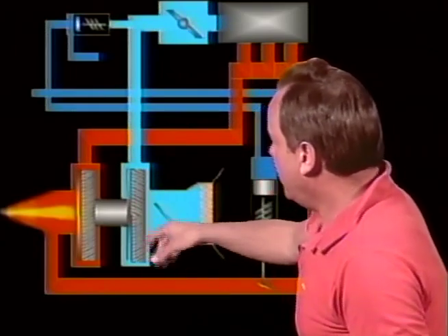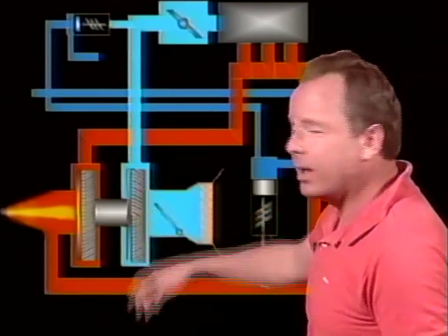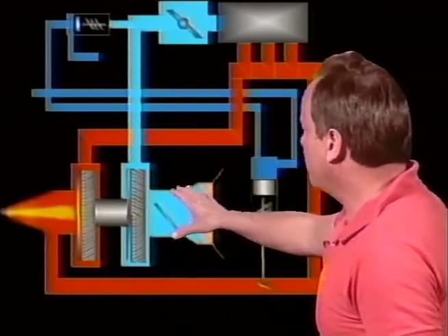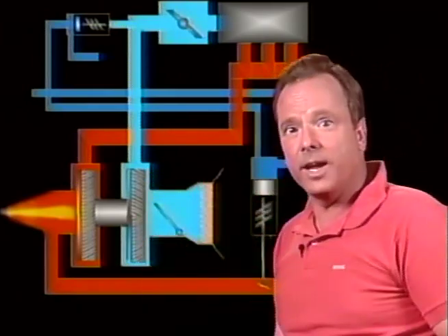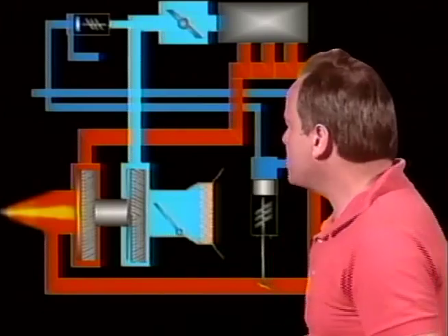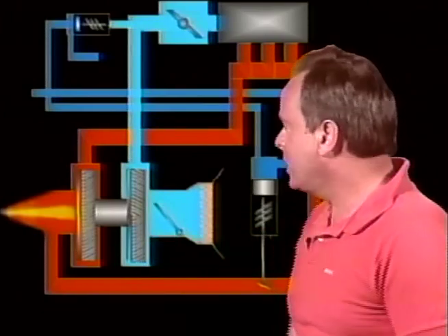impeller. And if you don't want to supercharge a lot, you'll select low-speed impeller, and if you want to supercharge an awful lot, put a lot of increased manifold pressure there, you'd use then high impeller in that particular case. They're going to ask you about switching from low to high impeller on the FAA written exam, and you're sitting on the ground, for instance, about ready to fly your Constellation, and you want to check to make sure that the supercharger is working right, so you shift gears in the supercharger. You shift from low to high impeller.